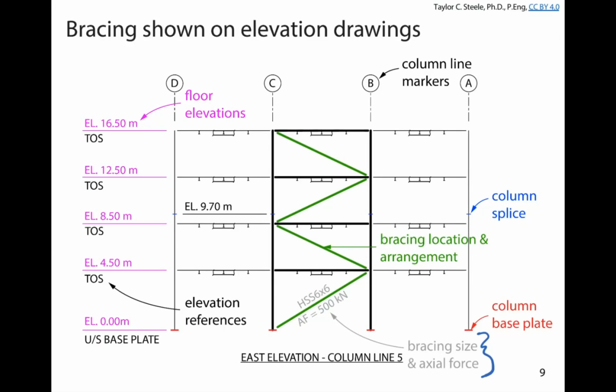And so we don't actually tend to design the connections as the primary structural engineer on the project. We tend to size all the elements and then give the forces to the connection designers to make sure that they can design those connections. Okay, so this is an important piece of information, and so on assignment 2, I've asked you what kinds of information might be important to carry forward to your drawings. On assignment 2, you're calculating some tension forces. You're not going to start factoring them until later, but on assignment 3, you'll factor those up, and you'll basically have a factored force that you need to consider showing on your drawings.